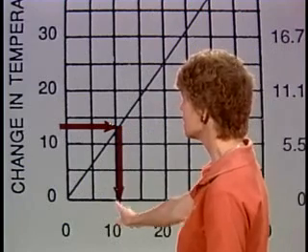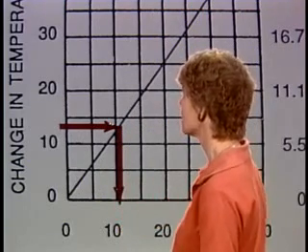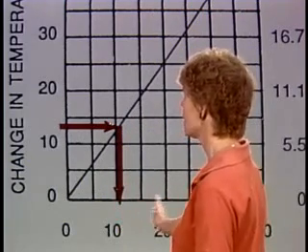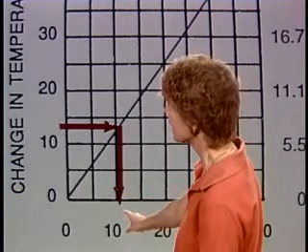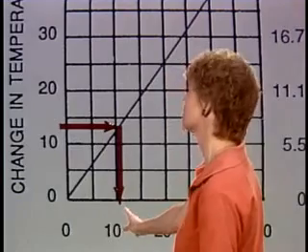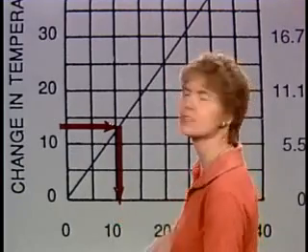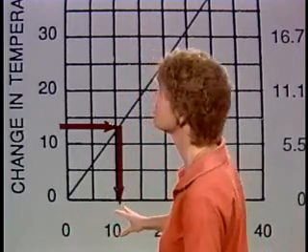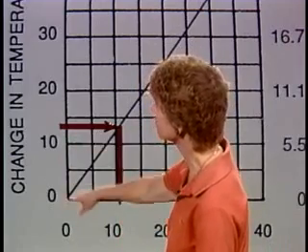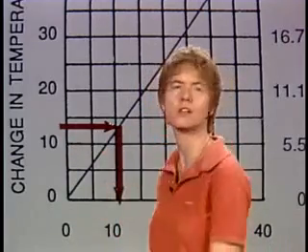The 10 vertical line is labeled, the 15 line is not, and the next labeled line is the 20 psi line. Where this arrow comes down, it's awful close to the 10, but not quite on it. It looks like about a 10.5 psi change in pressure would be allowed with a 13 degree change in temperature based on this chart.